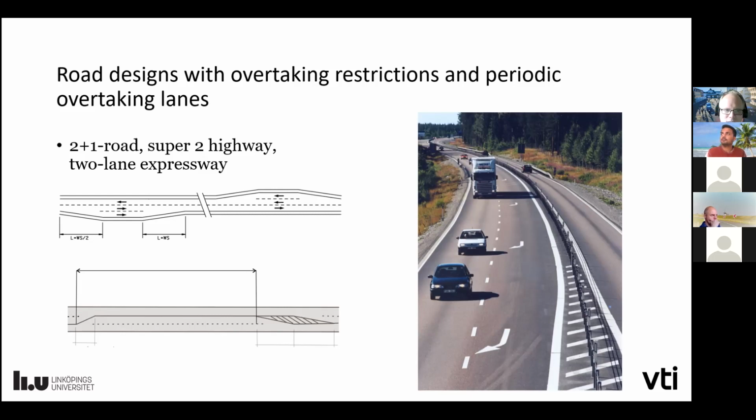Sometimes it's more that it's 1 lane in each direction and then some overtaking or passing lanes. The Swedish one is really the thought that in general it would always be 2 lanes in one direction. Of course, there might be intersections. As we see, the transition from 2 to 1 lanes also takes some of this area. So in principle, it's only about 45% of the length that's 2 lanes in one direction, but you could also sometimes have less than 40% two-lane segments.